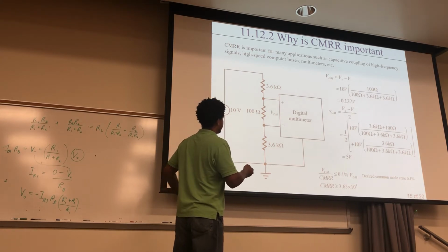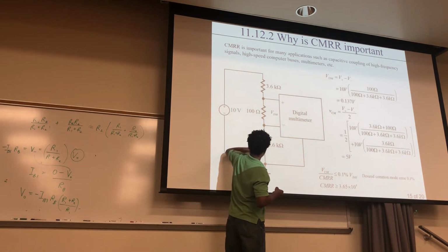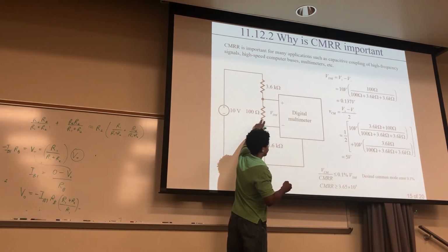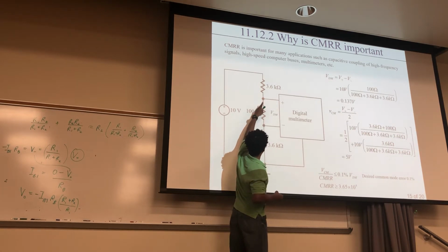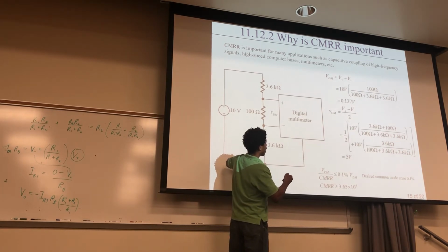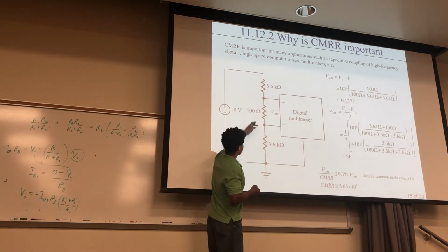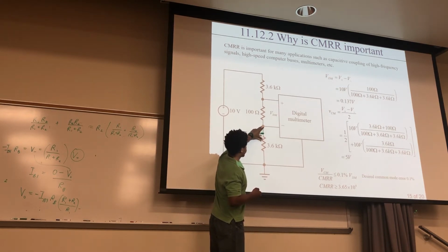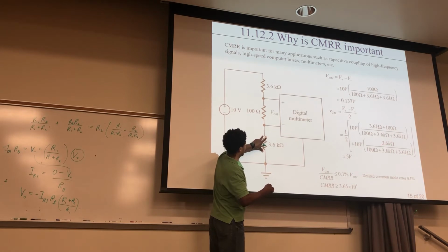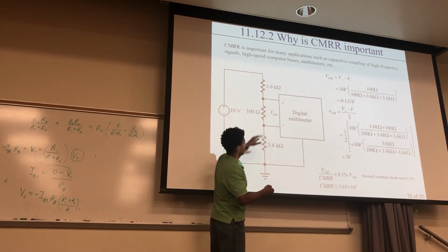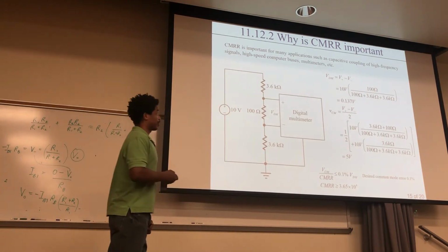It's going to be these two resistances below, before you get to ground. That's what this numerator is, divided by the resistances of the whole thing, all three of them. For V minus, it's just this point, which corresponds to the numerator of just this voltage, this resistance over all of them. And you work that out, that's 5 volts.